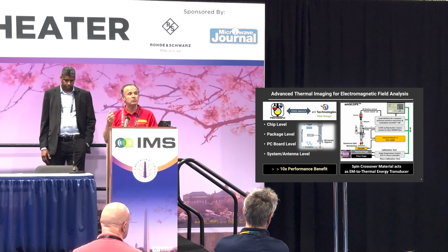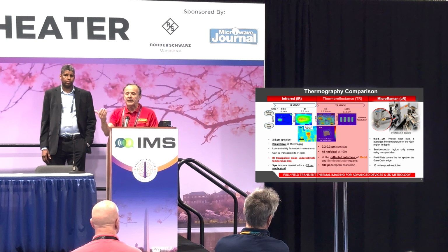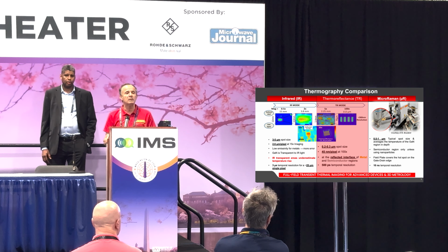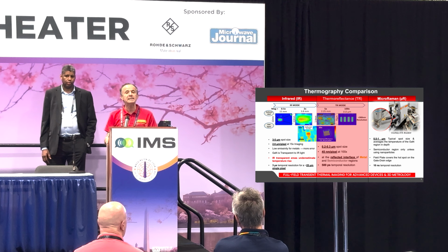In addition to that, there is an invention of a new material chemistry that can convert electromagnetic energy to temperature. By using that technique, we can use the same thermal camera to look at the devices under test. If you're not familiar with thermal imaging, infrared, most of you have heard, I'm sure. The challenge is that it is very slow and is also not the highest resolution. What we develop is what is in the middle, called thermoreflectance.